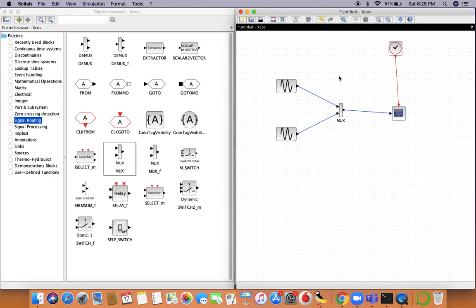Now, before we run the simulation, we need to decide how long to run the simulation for. So for our case, our angular frequency is 0.01 radian per second. So one full cycle will be 2 pi by this value of omega. So if we want to run it for 2 cycles, it will be 4 pi by omega. So 4 pi is roughly around 12.56, and that into 100 as it's divided by 0.01, it's 1256.